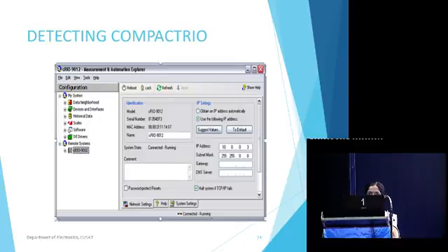For that we have to open Measurement and Automation Explorer. In that, under Remote Systems, the name of the CompactRIO will be displayed as shown on the slide. That is 9012, the CompactRIO we use. Then we have to go to network settings as shown here. Then we have to set the IP address and subnet mask. Then refresh the device. Now the CompactRIO is ready for execution.